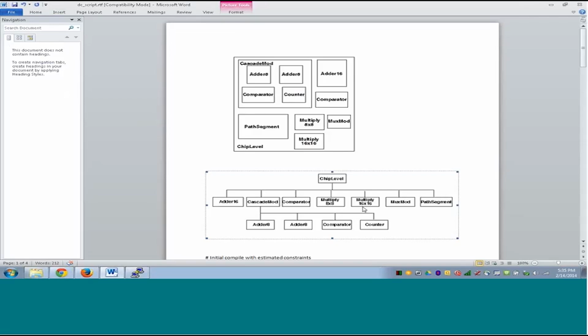Now whenever it was compiled the first time around, in the initial synthesis, the compilation did not optimize this path very well, because the input delay at the multiplier level was some non-optimal value. When the characterize command wrote out the new input delays, these new input delays were very realistic, and in the second pass compile, DC was able to do a better job.